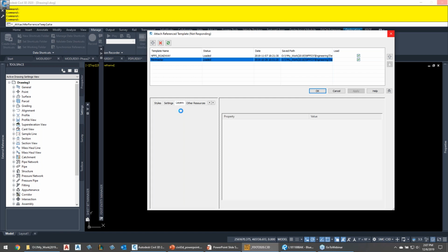So again, even if you just use it for AutoCAD stuff, that in itself is a huge time saver. How many times have you changed the layer properties in one file in the project, and you said, hey, you know what, I got to go change it now for everyone, or I changed my template, but then it only updates in the template, not any other files that were used when I did File New in general. This actually leverages and references this file so that if I open up the FDOT master or my NFPS roadway file, and I change a layer property or I add a layer, it actually automatically will proliferate through all the drawings that are pointing to that file. And that is just a huge advantage.